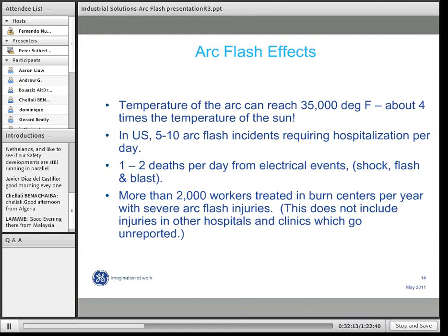So you can see there were two things that he did wrong. First of all, he did not de-energize everything when he did his lockout, tagout, and applying of safety grounds. And second of all, he didn't look carefully enough behind where he was drilling to see that there was in fact a cable there. So this actually occurred in the switchgear room of a hospital.